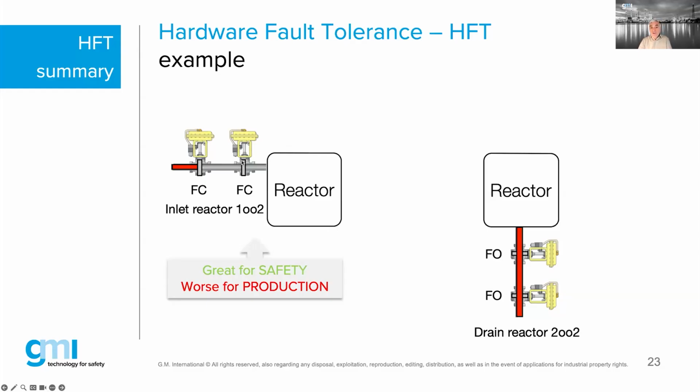They hate seeing 2 valves in the inlet, because they know from production availability that if either one of them closes, they lose their production, and that doesn't make them happy.